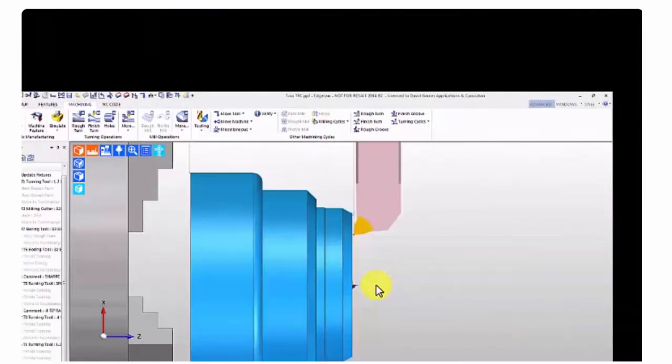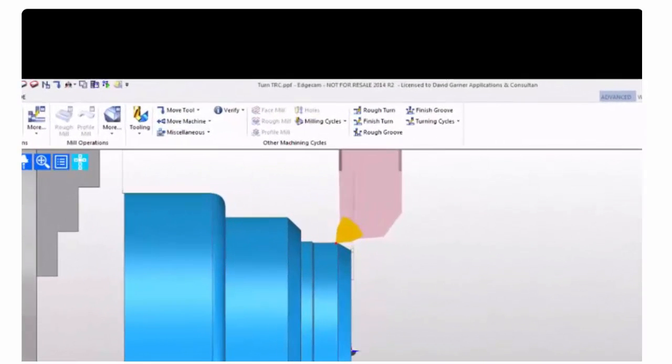We've got two G codes for tool nose radius compensation. G41, which is to compensate to the left, and G42 to compensate to the right. So if we were to machine around this component like that, if you imagine that you were behind that tool, in other words you're back here behind that tool, it is to the right of the component, so that would be using G42.